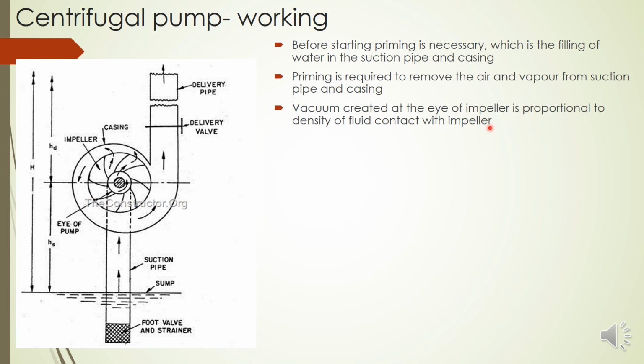Water is 1000 times denser than air. So if air is present and we simply rotate the impeller, we will not create any vacuum, so the pump will not lift water. That is why priming is important. So what is priming?